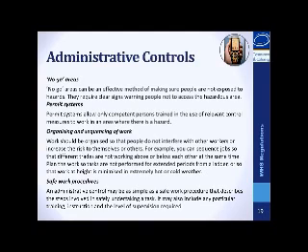Administrative controls. Administrative controls can be used to support other control measures and may include no-go areas, permit systems, the sequencing of work and safe work procedures. Using administrative controls exclusively to minimise the risk of falls is only appropriate when it is not reasonably practicable to use a high-order control.